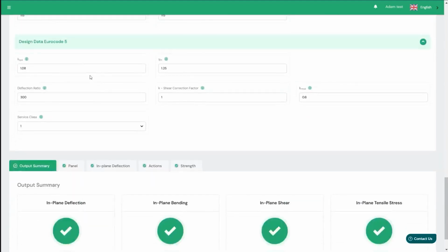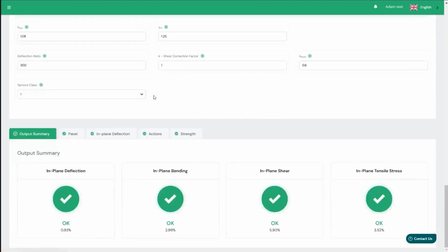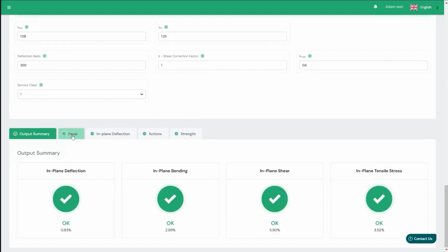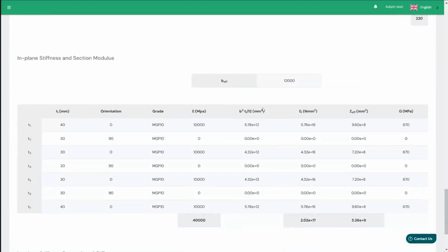All right, so that's the lamellar width, also impacts the in-plane shear strength. And finally, you got your design data to Eurocode in this instance, and you can follow the more information to understand specifically what there is and get it more to the local context as best you can. So if I go through the calculations, you can see the scope of the check. So right now, as you'd expect, it's a big diaphragm working as one. So you wouldn't expect the utilization to be so high, but I'll follow through the calculations now.